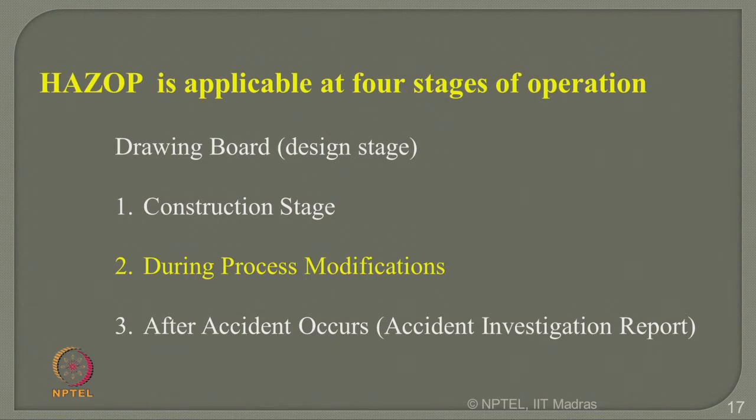It can also be done at the construction stage. It can be done during process modifications, and can also be done after an accident occurs, which we call AIR, that is, accident investigation report. HAZOP studies can be done as early as the design stage, even as late as post-accident scenarios. So, HAZOP is one of the very powerful tools generally used in oil and gas industries to revisit accident scenarios and to prevent or mitigate the possibility of accidents occurring in the plant.